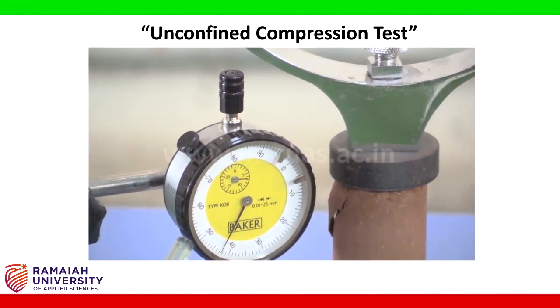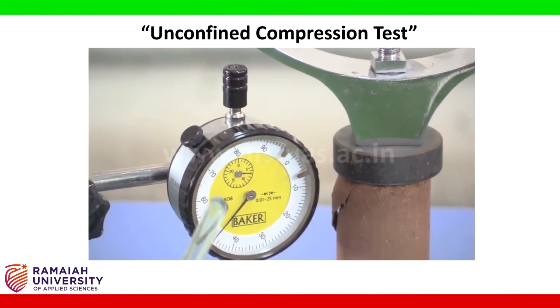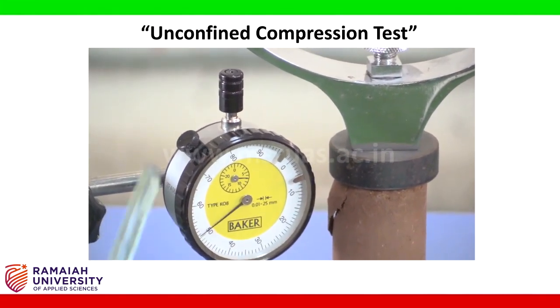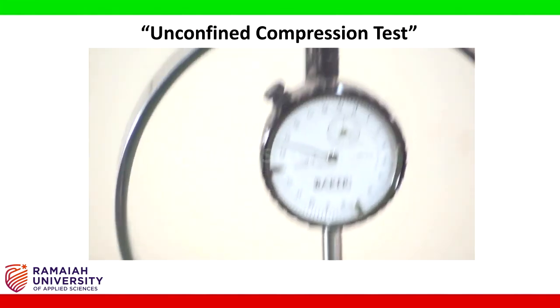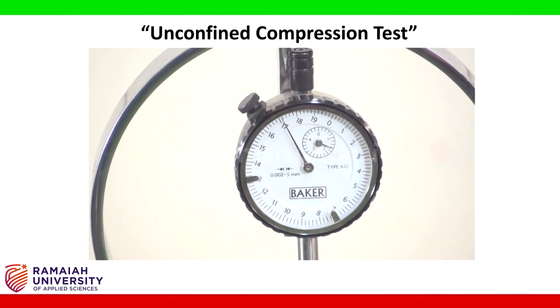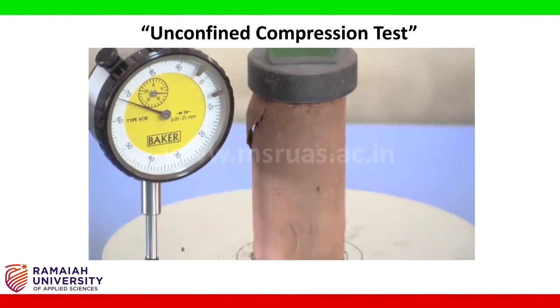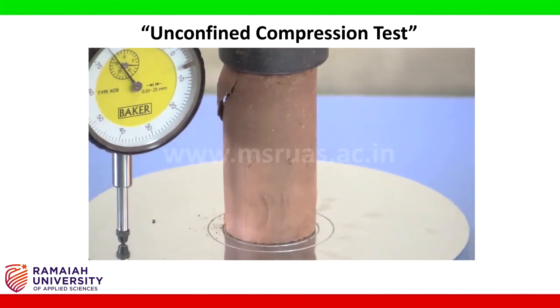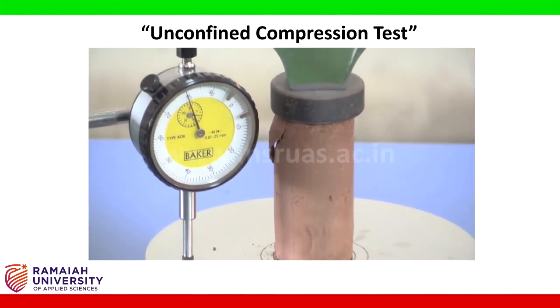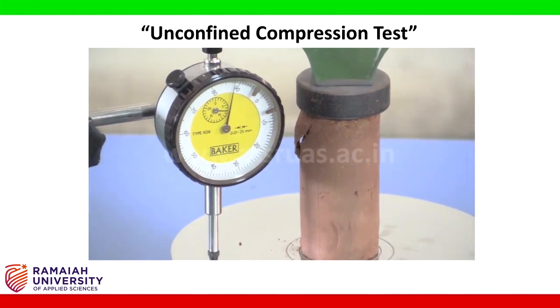Now observe the readings till the deformation becomes constant or it starts decreasing. You can observe the formation of cracks also on the surface of the soil sample. For each reading you can measure the time also.